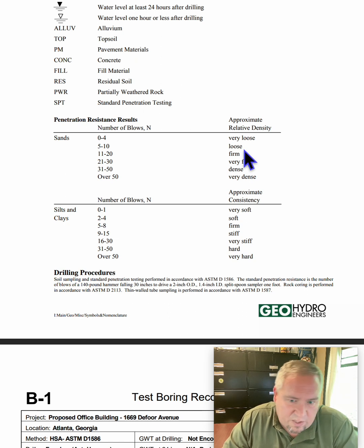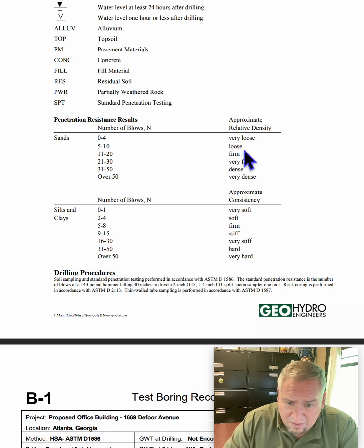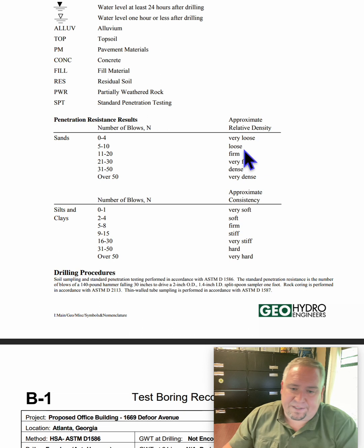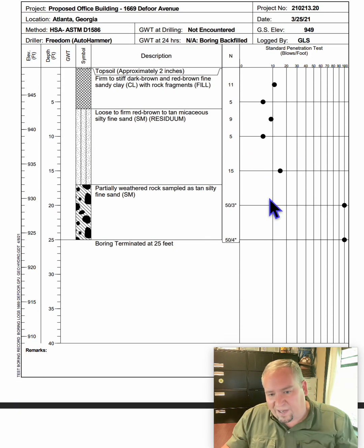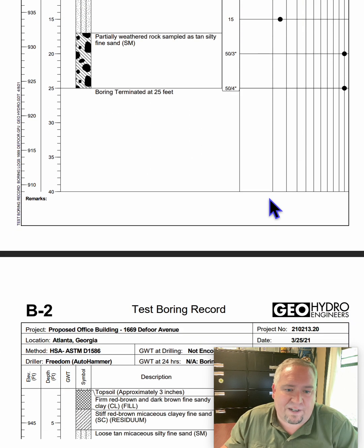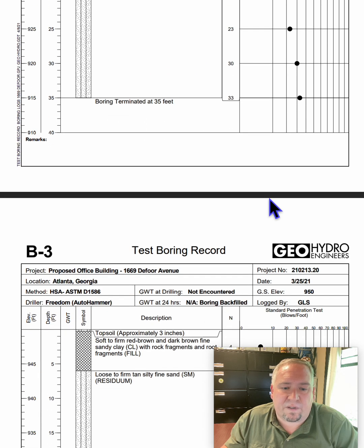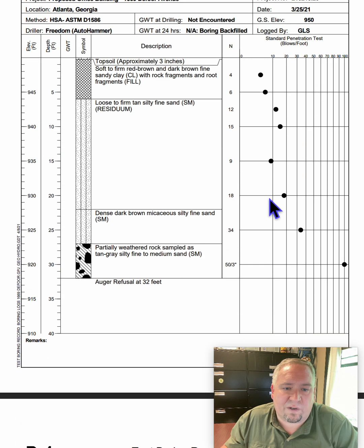Now, loose soil can also indicate a sponge for water, and so high moisture content. So they can cook the dirt and tell you the moisture content. You may pull that dirt to the side and let it dry. Any of that loose stuff, let it dry. Have them check it and find out what the quality of it is.